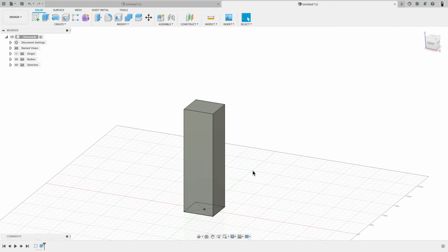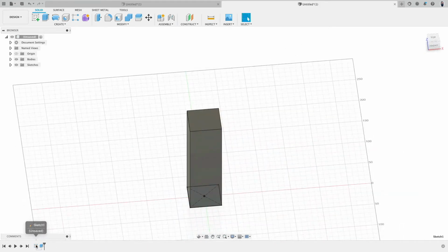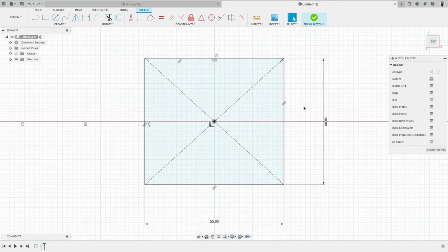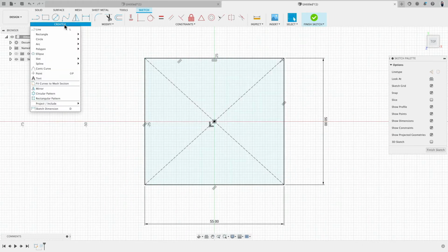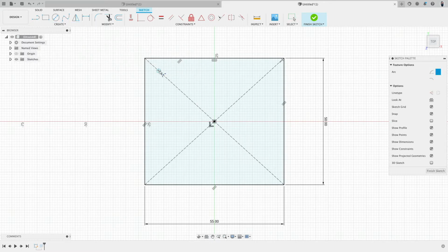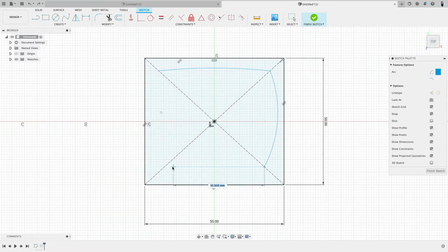Now we would go into the wood shop and take a bandsaw and curve all these sides, or basically use a sander. Okay, so let's add this detail in the sketch and then we update our extrusion. To create the curved sides, we will use the arc 3-point command. So click, click, and click. I'm just loosely positioning everything. Oops, this is too aggressive. Right click, repeat.